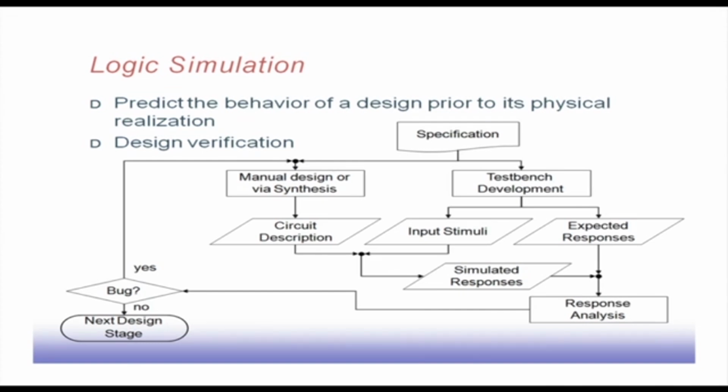So, logic simulation predicts the behavior of a design prior to its physical realization. Suppose we have got a circuit to be designed, and we have generated some test pattern set for that. Now how do I judge the quality of this test pattern set? One possibility is that once the chip has been fabricated, we can apply those test patterns and see whether it is detecting some faults that might have crept into the chip.